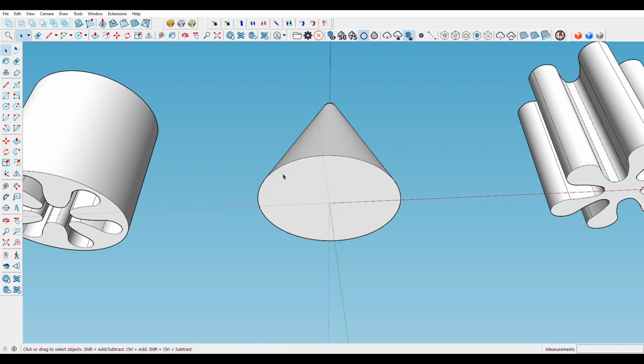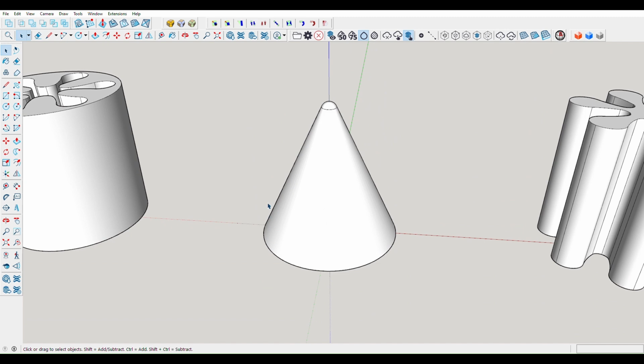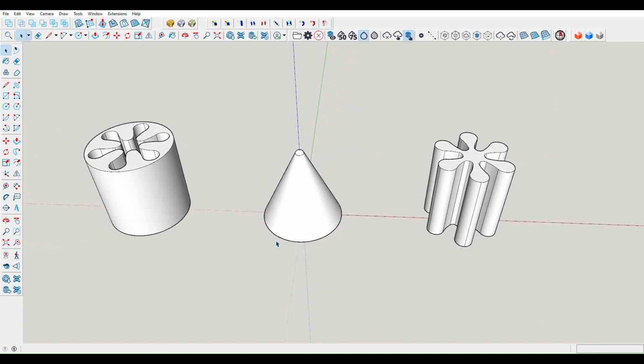We could now use the solid inspector tool or look at your instances to see if these are solids. I'm fairly confident we're good. Now what we're going to do is move this object into those two spaces. Well, first of all we need to make everything groups, so we'll group each object by double clicking to select all, press the G key to group and create the groups.